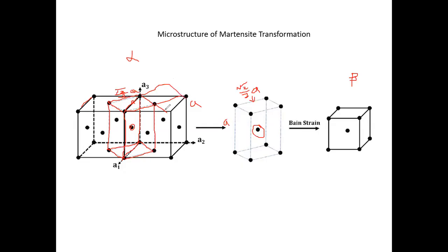You can do this for the entire structure to construct many of these cuboids. I wouldn't be able to show that in here, but I can just outline what you see. So you're not using the original cubic system to look at the periodicity of the FCC structure, but you can perfectly well use this cuboid to look at FCC. And this particular cuboid I'm showing here is a fundamental repeating unit for that structure. So basically, the whole FCC can be constructed by repeating this cuboid many, many times along the 2 orthogonal directions. Okay, so that is the first step.